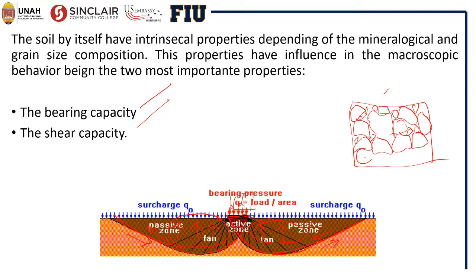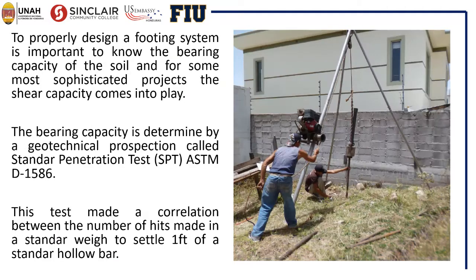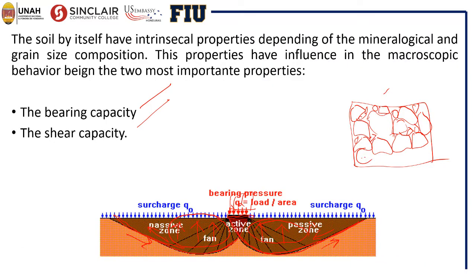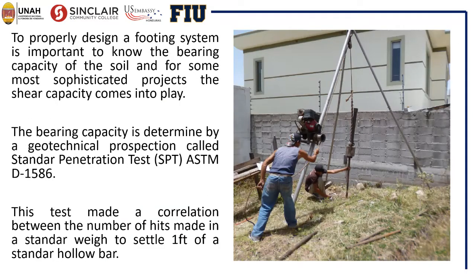To determine these two important properties, the bearing capacity and the shear capacity, we have to do a geotechnical prospection. For most simple projects, the bearing capacity is enough, and for some more sophisticated projects, we need to perform a test, especially to determine the shear capacity of that soil. Okay, the way to determine the bearing capacity of the soil is through a standard penetration test. The standard penetration test, in simple words, is a correlation